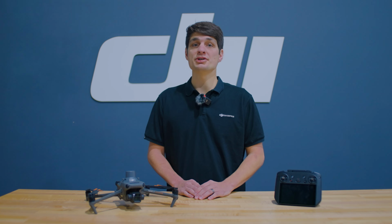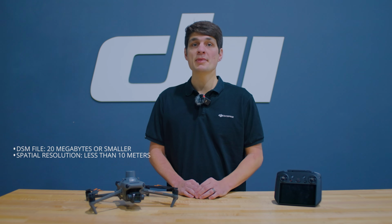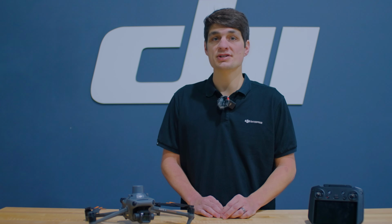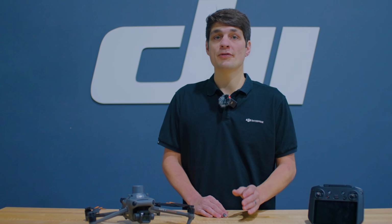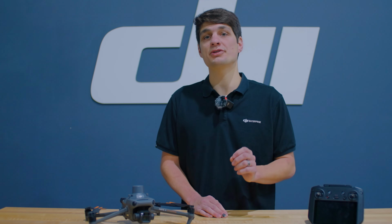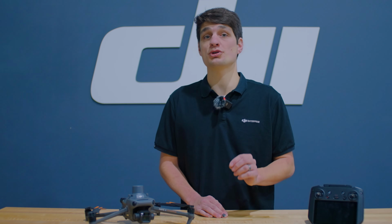Some key points on your DSM file: make sure that it's 20 megabytes or smaller and has a spatial resolution of less than 10 meters. Utilize WGS84 or EPSG code 4326 for coordinate reference system. Vertical datum for elevation data should be ellipsoidal. This mode, while tedious, is the most accurate way of terrain follow. This also allows you to fly much lower than real-time terrain following.